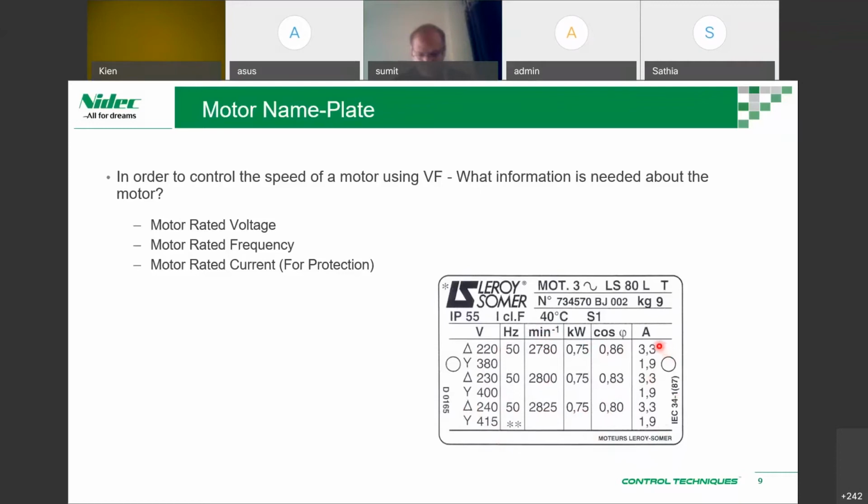And you can see the ampere current rating. This current rating is to protect the coils of the motor. When we are using drives, it would be like 150% or 200% of control to make sure you don't burn the coils with overcurrent when there's a locked rotor condition, when the load is not moving, and you're just trying to push too hard.